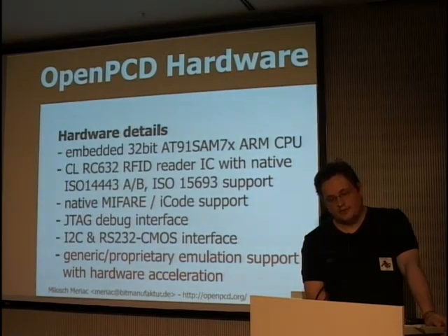Harald wrote a great bootloader, which is able to be refreshed instantly during runtime. It only takes a few seconds, and you get a new firmware. You don't have to press strange key combinations or buttons on the device. You can instantly flash it, and this results in a very quick programming style, because you can, for example, create a target that says make install, and it immediately uploads the changed code, and with the debug interface you have a perfect overview of what's going wrong.